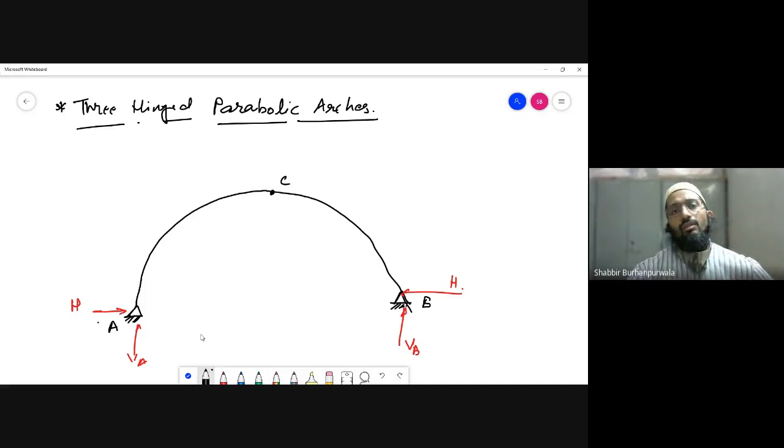The solution, the methodology, everything would remain the same. Okay, the only thing is that in symmetric arches, whether there is loading or something, the bending moment diagram and some properties are predictable. But when it is unsymmetric, then the things are not predictable. But they are determinate. Means you can calculate, you will be able to find out its answers.